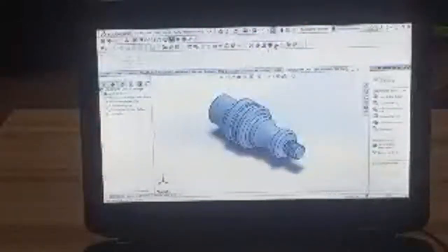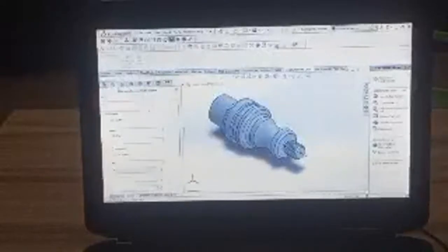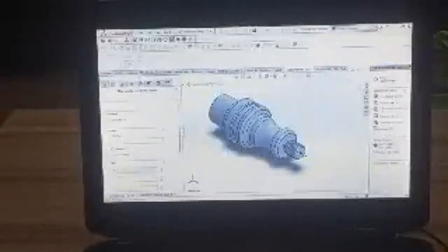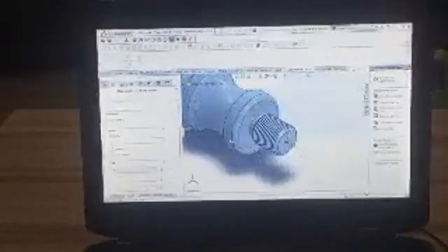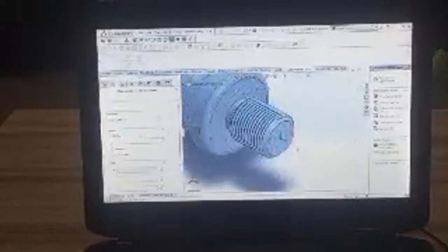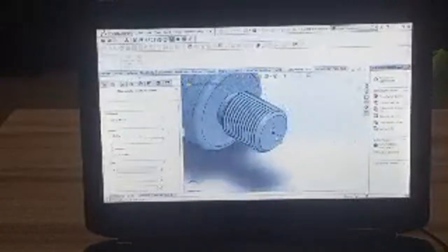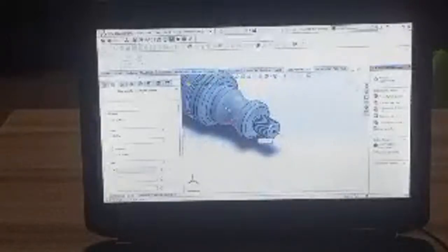You can come here and now define a coordinate system where the part origin is the X0, the Y0, and the Z0. But because we're using a lathe, it's going to use the X and Z axes. The beauty of SolidWorks CAM is that when you take on the add coordinate system, all of them have been user defined, so you can change the points. Maybe here, this point here.